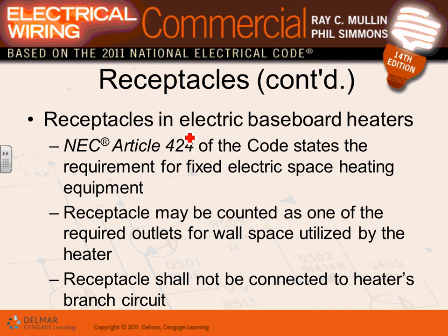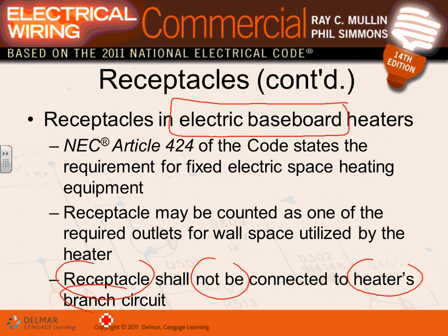If you have a built-in baseboard heater, in commercial and residential, they have baseboard heaters with a built-in receptacle. Two things: if you have a built-in receptacle in a baseboard heater, the receptacle shall not be connected to the heater circuit. So you have to have two circuits: one going to the receptacle and one feeding the heater.